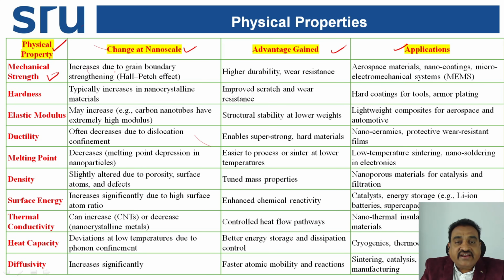It increases due to grain boundary strengthening, that is called the Hall-Petch effect. The advantage is higher durability and wear resistance.